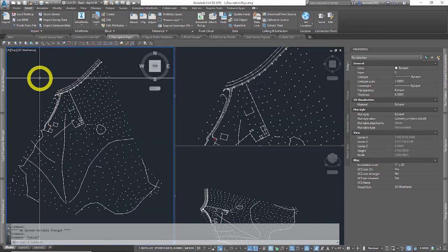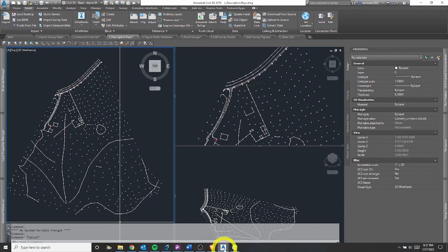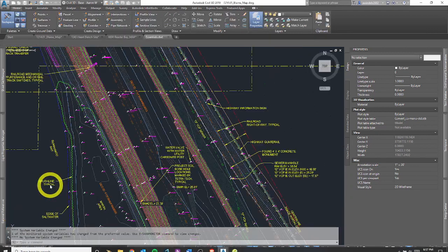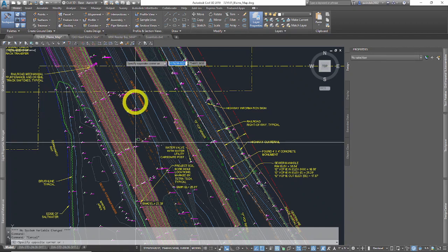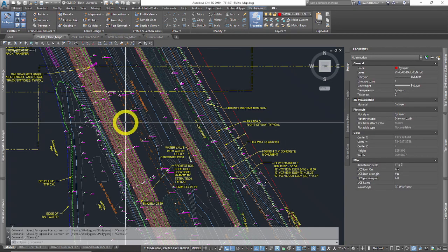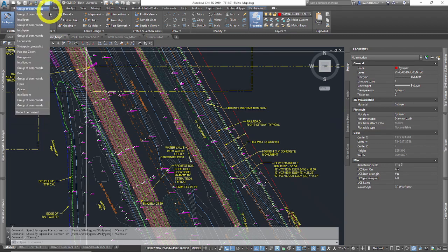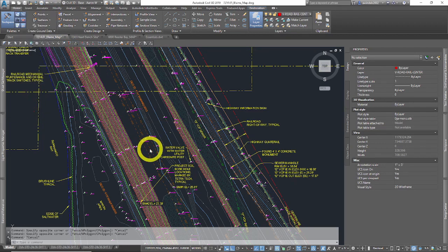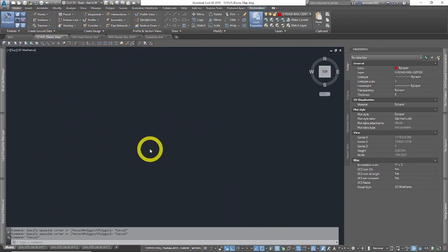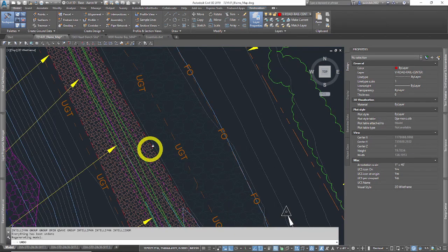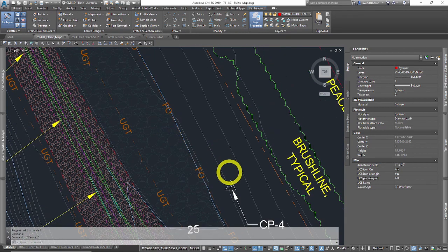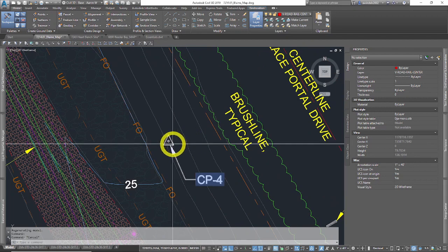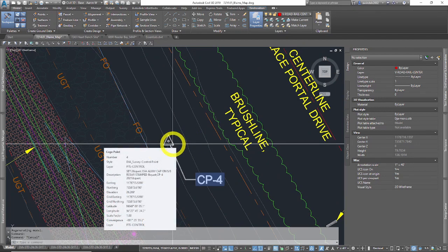And description keys basically, if we go to a different map that I've done somewhere else, a description key dictates a lot of things, but mostly how a point comes in, on what point style, what point label style it comes in on, and also what layer it comes in on, which layer also gets controlled by point groups. They go hand in hand, description keys and point groups.